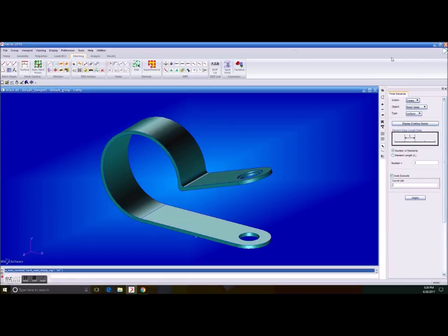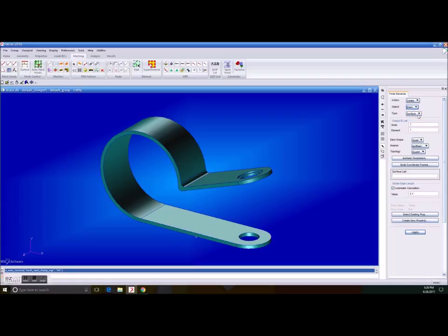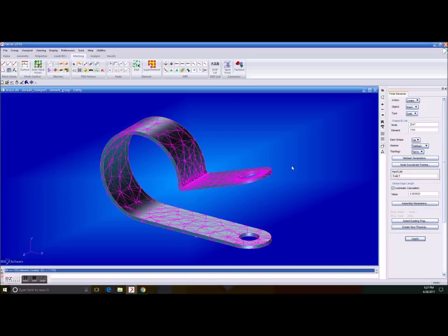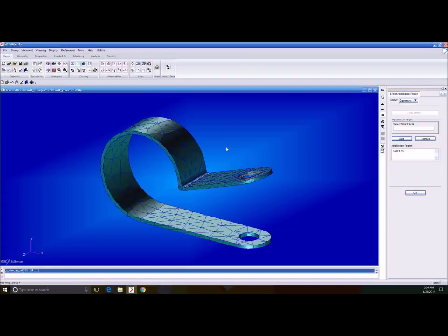And the next step that we're gonna make is to mesh the solid. For that, we go to the meshing tab and we need to make sure the create mesh and then solid. Then we need to make sure that TET mesh and TET 10 are all selected. We're gonna click on input list and screen select all the solid. We're gonna leave the automatic calculation and marked and click apply.